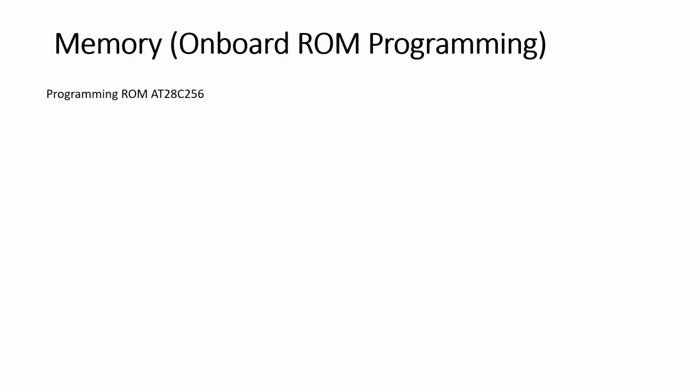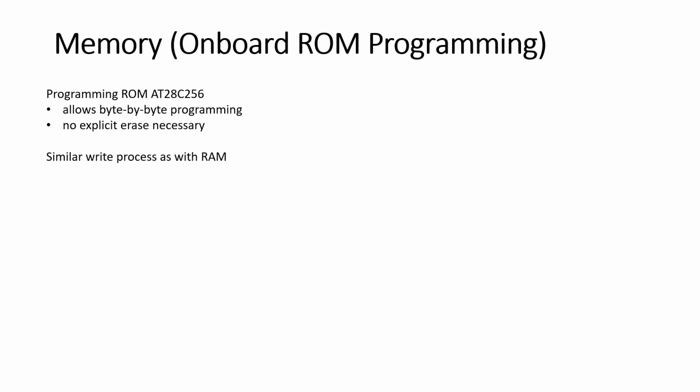One interesting thing about that EEPROM that I use for my read-only memory is the way that this chip can be programmed. It's not only that it allows byte-by-byte programming, so I can just put in a single byte. I can also put that in without explicitly erasing the byte or the area before.